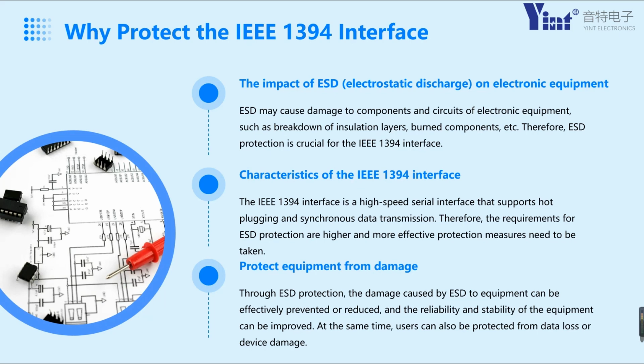Characteristics of the IEEE 1394 interface. The IEEE 1394 interface is a high-speed serial interface that supports hot plugging and synchronous data transmission. Therefore, the requirements for ESD protection are higher and more effective protection measures need to be taken.